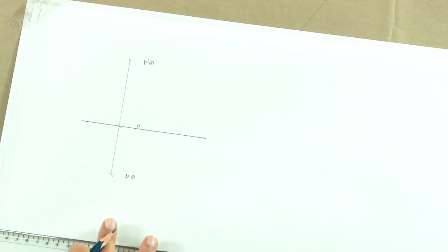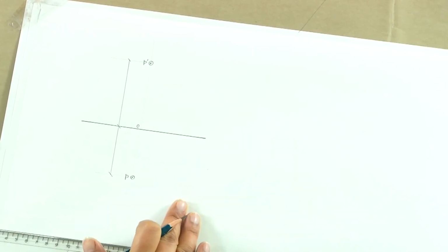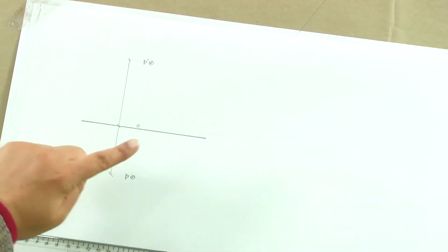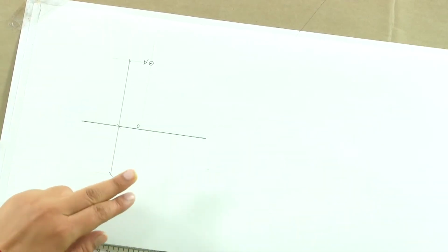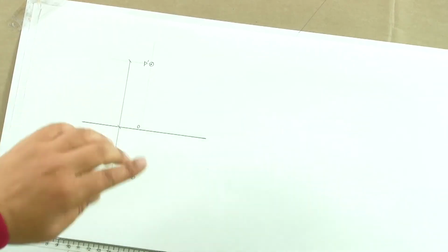If you remember, we always had to mark the dimension towards the left preferably and to the bottom. Now, there is no horizontal dimension which has to be shown towards the bottom of the drawing. So, we just have this. Now, you always have to remember, the distance from VP is shown in the top view and the distance from HP is shown in the front elevation. Often we make a mistake about that.